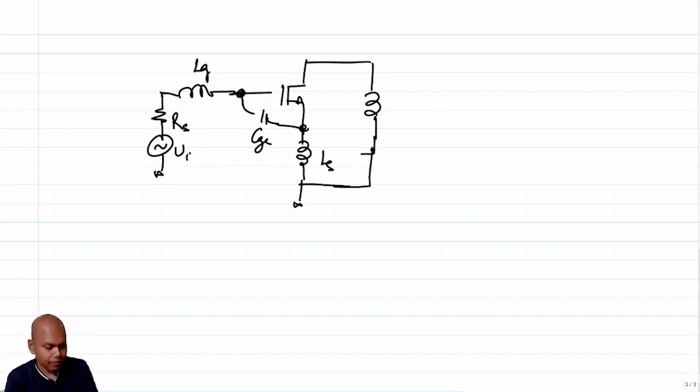Ultimately we are designing this LNA for a reasonably large gain, which means that for some amount of swing at Vi, you are expected to have a decently large swing at the drain of the transistor.